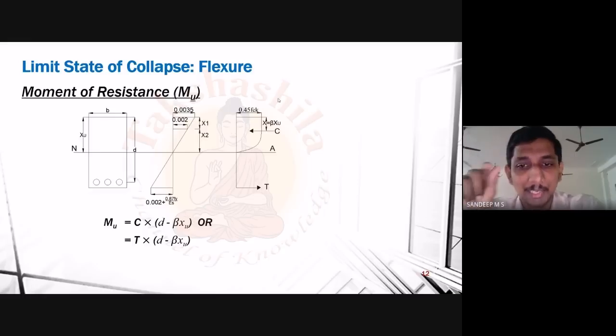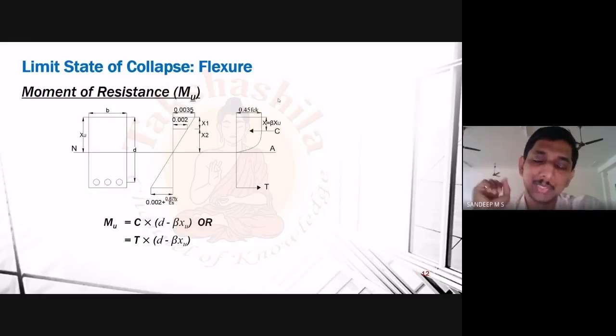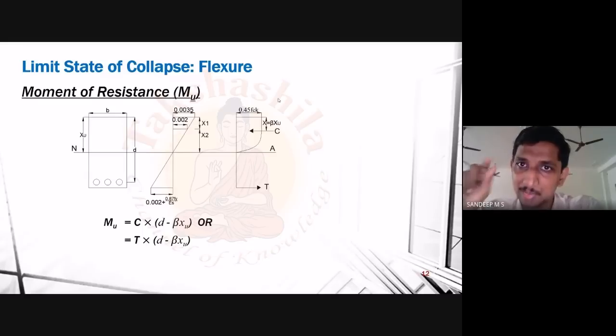So basically, due to this fact only, we are using the second relation, because my steel is actually failing first. And in order to cause the yield strain in concrete, I require a higher load. So it is based only on the amount of load that we are externally applying. Say in this case, we were applying from 0 to a higher load, right?